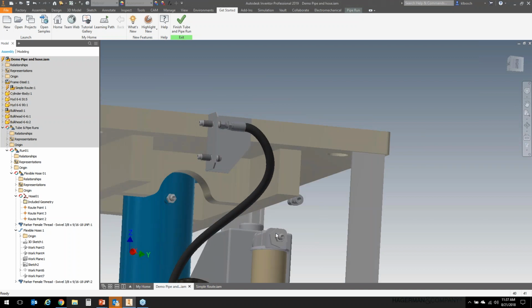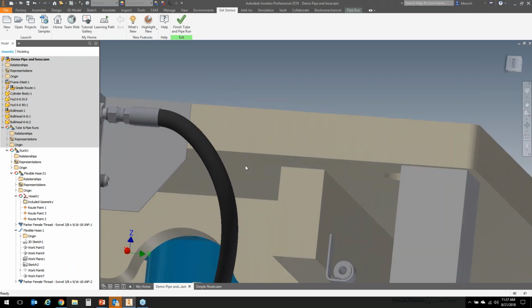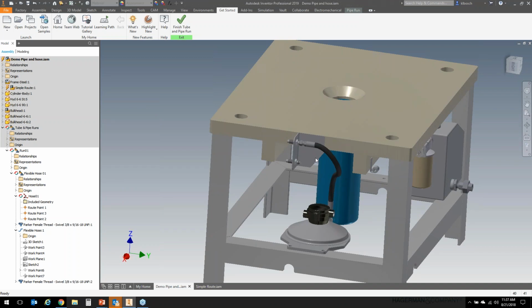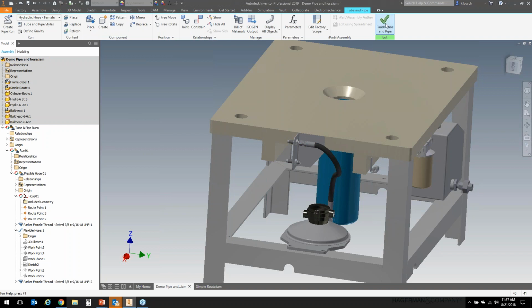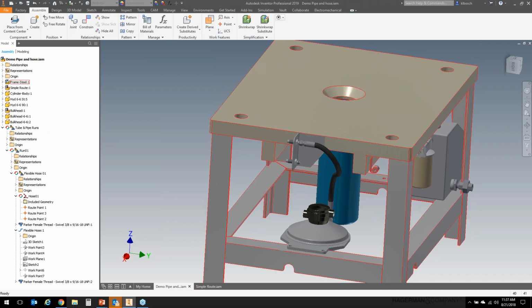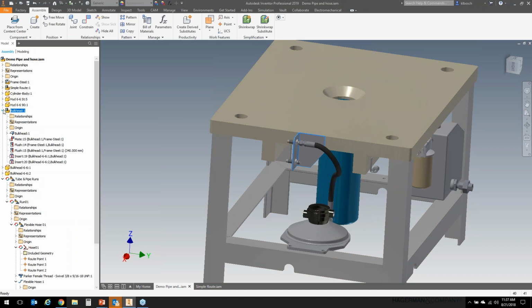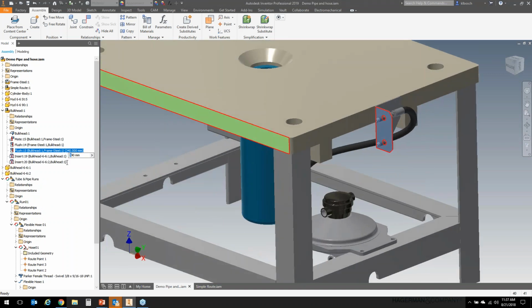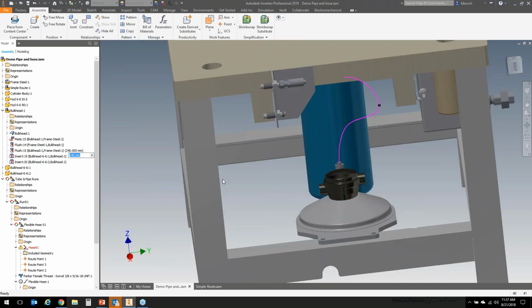And I also have to meet up with that offset point. So for instance, and I did this one a little bit earlier, we can break this simply by having that as defined. If I say, you know what, I'm going to finish my edit here, and I want to move that bulkhead. I've got that bulkhead set at a 340 millimeter offset. If I change that to, say, 240, well, all of a sudden my hose breaks.